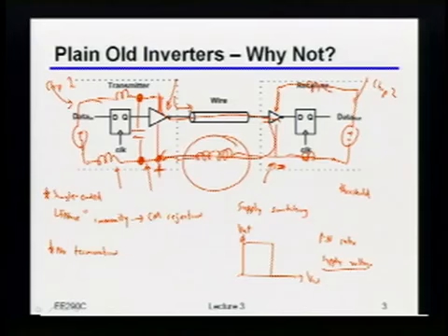Turns out that similarly, even if you looked out on the channel over here, that backplane with the connectors and so on, if you put really, really sharp edges in, then every single tiny little discontinuity that may be physically small, you'll actually be able to see, right? Because a sharp edge implies a very, very small wavelength, right? So from a crosstalk standpoint, a lot of times you really want to control how fast you change states, just to make sure that you don't end up exciting a bunch of extra junk all over the system that ends up killing you somewhere else, that could be very complex to figure out exactly what was causing that crosstalk in the first place.